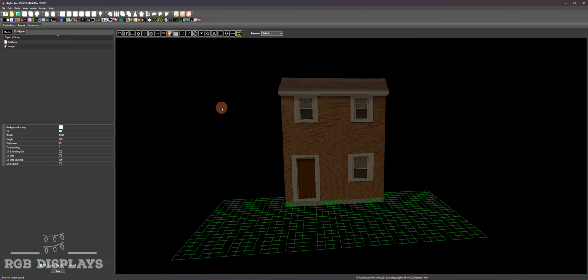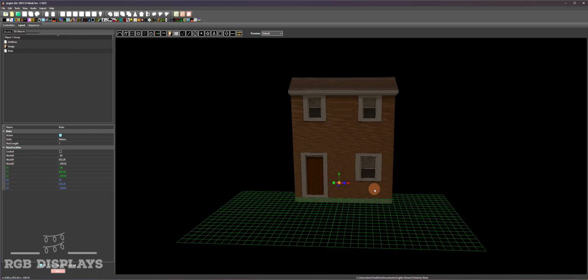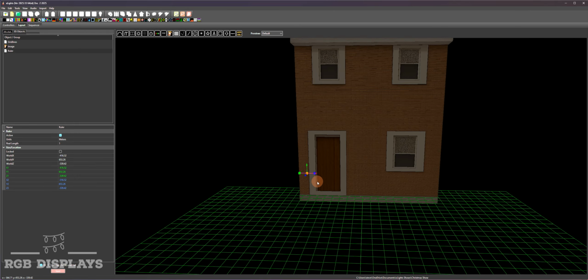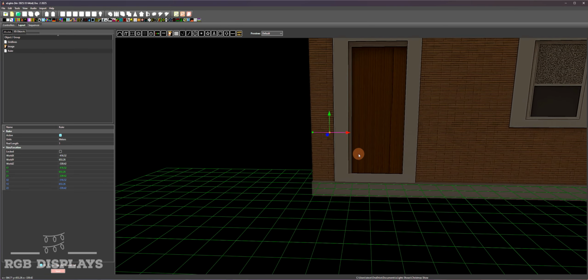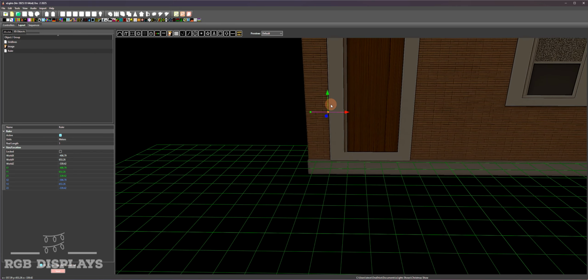To begin, click Add Object, then select Ruler. A ruler object will appear in the preview window. Using your mouse, move the ruler so it sits against the house image near the door in my case. We now need to stretch the ruler to match the horizontal dimension measured above.